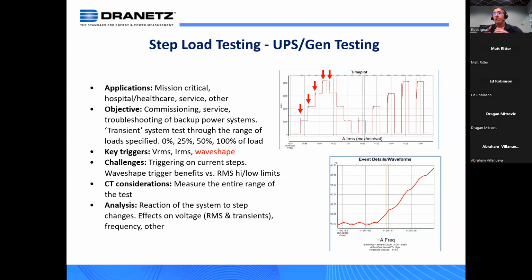Okay, so next one is the step load testing. And we've done sections of webinars on this. And really, this is extremely important for applications such as generator testing, mission critical testing and applications like that, and really in hospital healthcare, internet applications, cell phones, or cellular data centers, things like that. And it's very common that they're basically inducing loads and they're stepping loads into the system that represent 0 to 100% of the capacity of the system. And what they're looking for when they step these loads in, what is the reaction on the voltage, the frequency, and maybe some other parameters that are of importance to them.